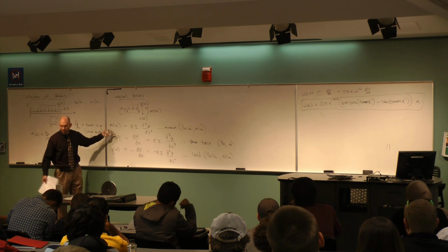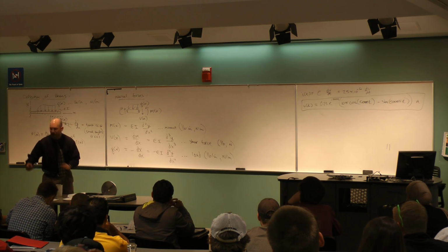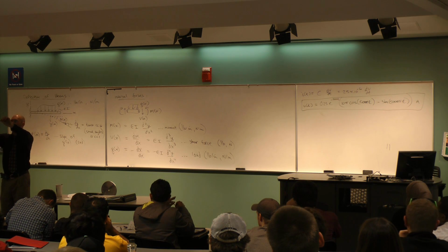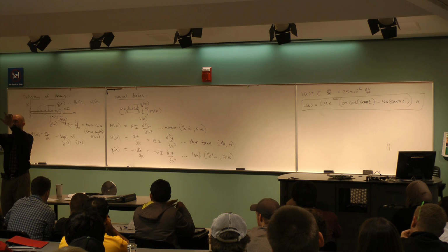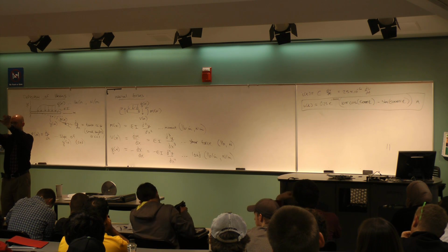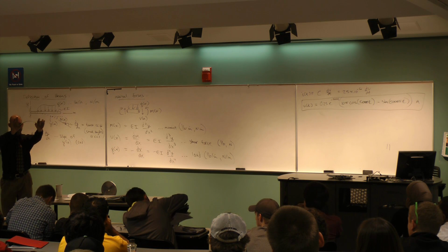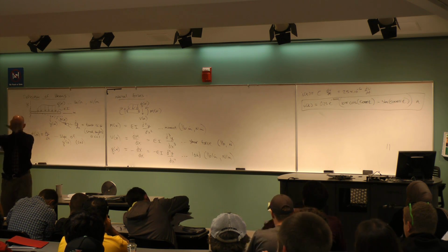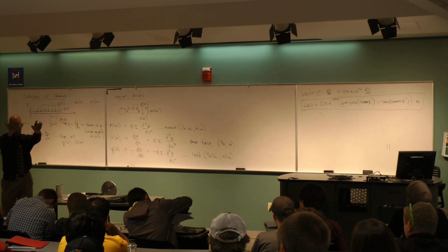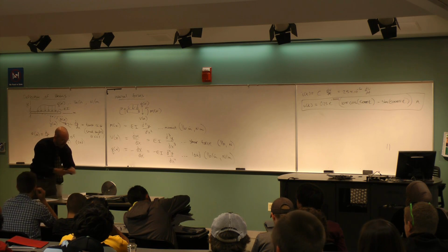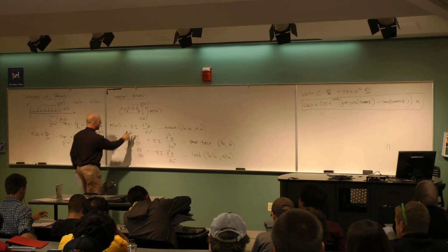So the moment, look, why does this work? If I want to bend a beam, how do I bend a beam, right? I got to put it between my two fingers. They're a distance apart from one another, and exert force times distance, right? When I do force times distance, I get bending. What's the shape of this thing? Yeah, it's a concave down, smooth curve, right? And so it makes sense that the second derivative, the bending, is the concavity, but I got this EI in here.